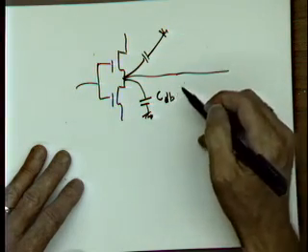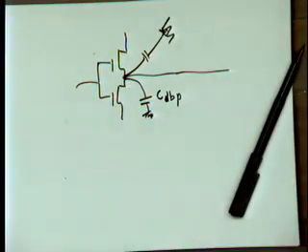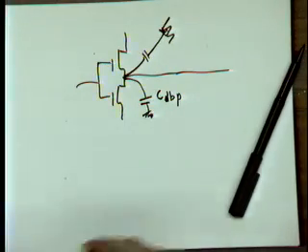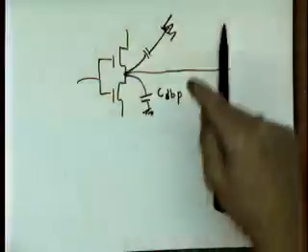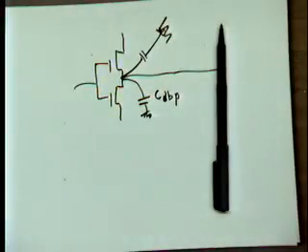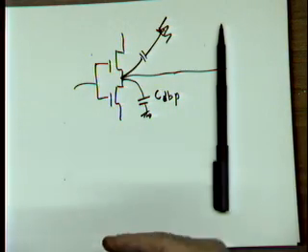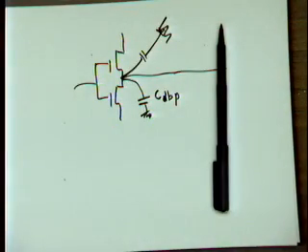Why can you call that ground even though you're not using small signal? Doesn't matter. It's a capacitance to DC. It's still going to give you the same charge displacement. Anything which is from a capacitor, when I charge it up and I look at the equivalent capacitance, I really figure out how much charge I have to supply. If this thing is fixed, it doesn't really matter what voltage it's at. As long as it's a fixed voltage, I'm going to have to provide a certain charge to move the voltage across. All right? So as long as it's DC, you don't worry about it. You can actually lump a multi-capacitance to ground.